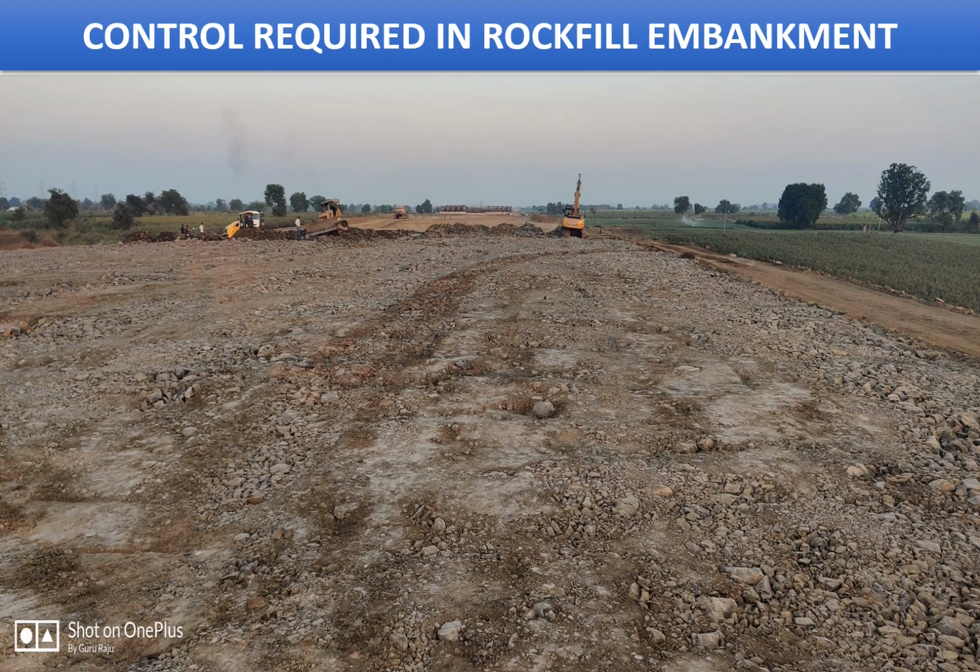The controls required can be shown, like the rock fill is being done. On top of it, you need to have a layer which will facilitate the rollers to move freely, and then do a static compaction on top of it.